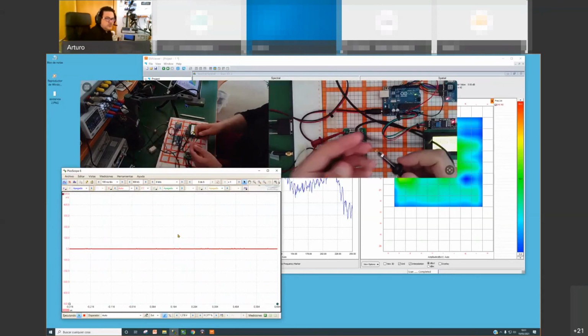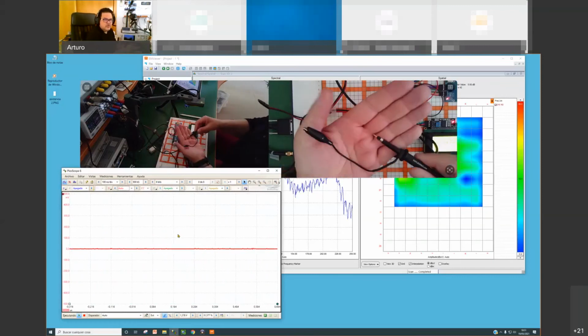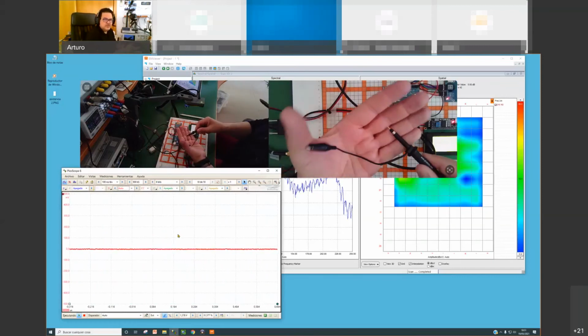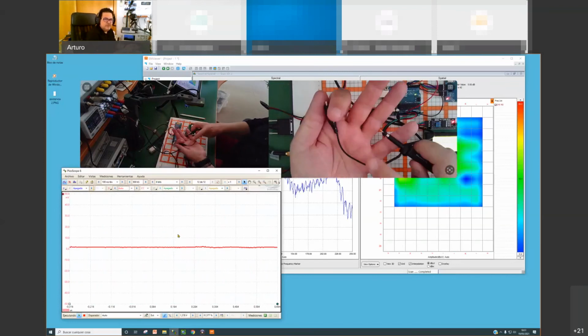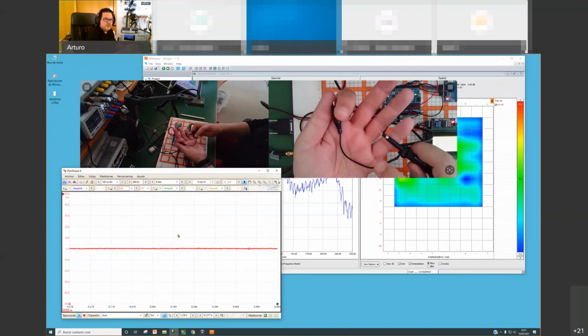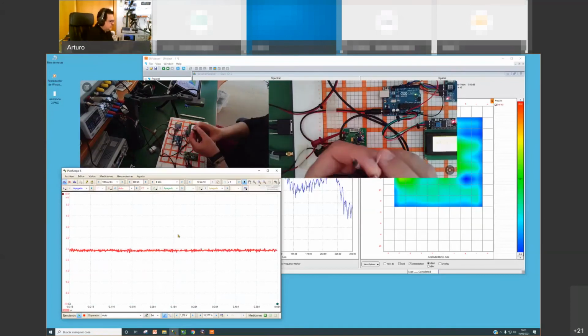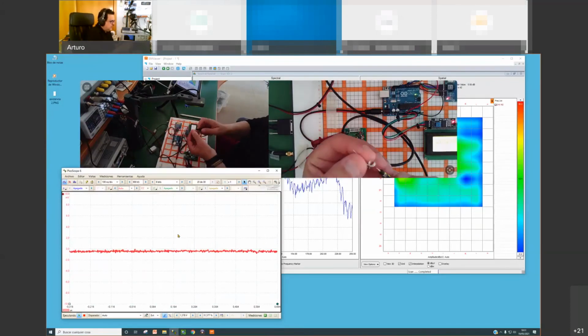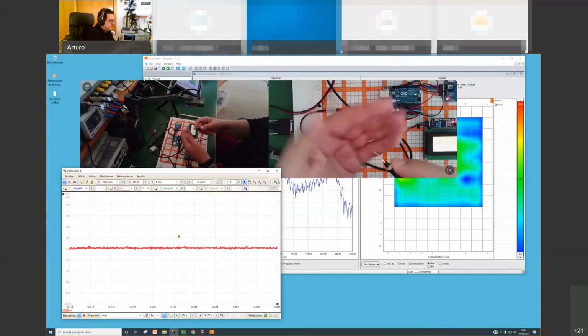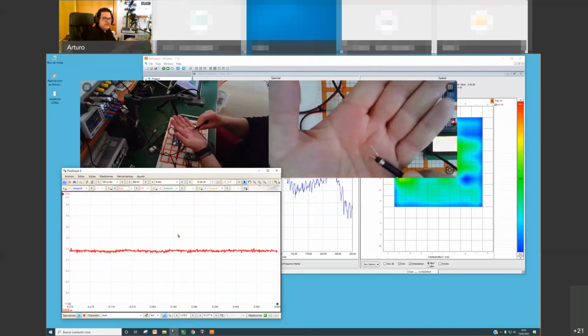Remember, if you try to measure any signal that is more than some kilohertz in your circuit, be careful about the pigtail of your probe. What I am going to do is to take a piece of wire, and we will be using this technique to minimize the possibility of creating the ringing in our probe.